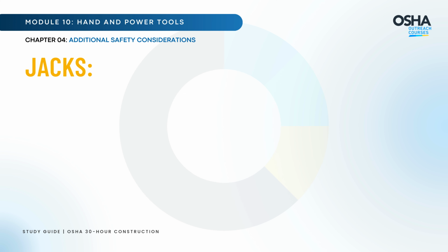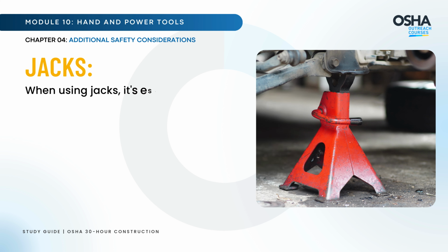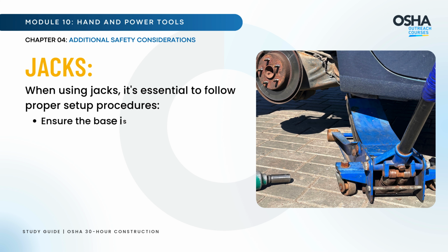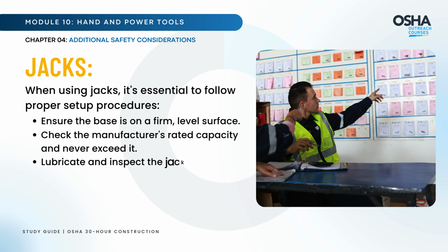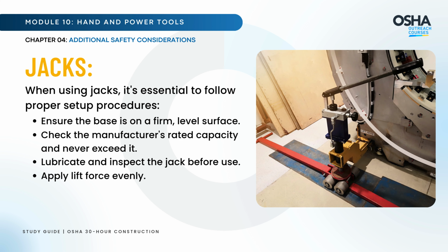Here are jacks. When using jacks, it's essential to follow proper setup procedures. Ensure the base is on a firm, level surface. Check the manufacturer's rated capacity and never exceed it. Lubricate and inspect the jack before use. Apply lift force evenly. Use a jack with a stop indicator.